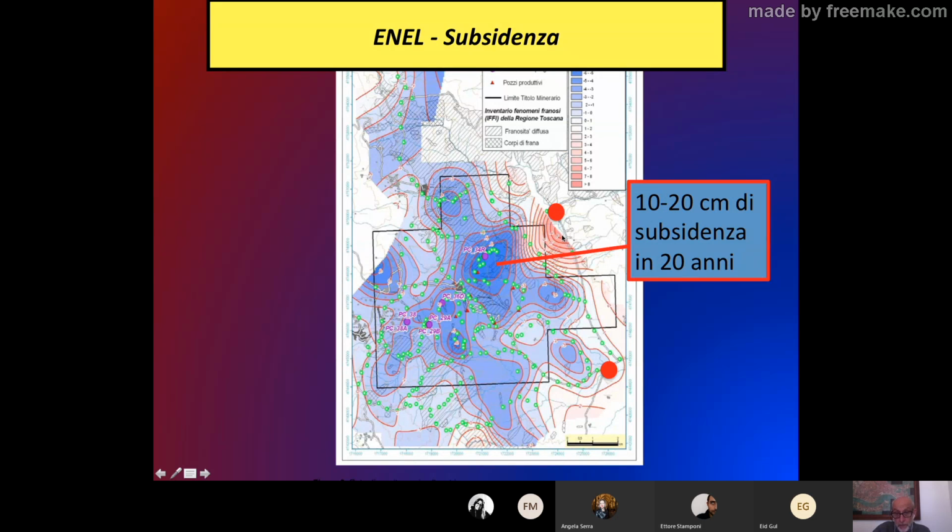Here you have about 8 centimeters up, and down here you have about the same amount downward. So the subsidence is probably the sum of these two values, so about 10-20 centimeters of subsidence in 20 years, about a centimeter per year. So the ground goes down about a centimeter per year.